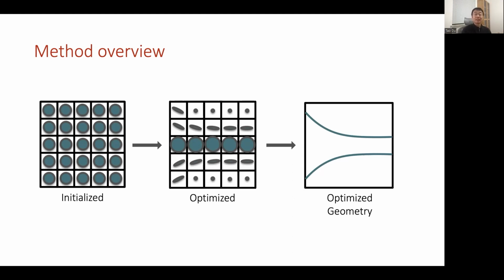And this constitutes a possible design involving solid, fluid, and their interaction. Our goal is to come up with a computational method so that we can optimize these designs by manipulating the parameters inside each of the voxels, so that a legitimate design can emerge, like what we show in the middle. Essentially, we can extract the boundary, reconstruct the actual geometry of this device,